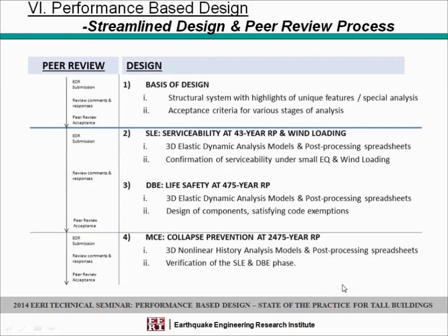Then you basically validate your desired or expected or conceived performance and behavior in linear and nonlinear domain by being verified in the MCE analysis of the 2475-year earthquake.